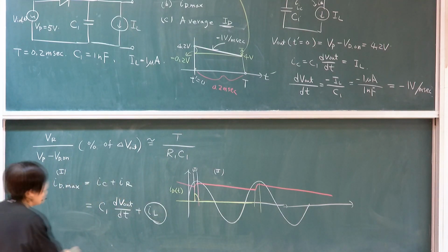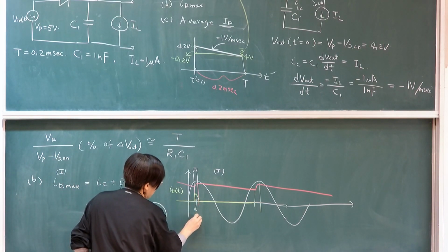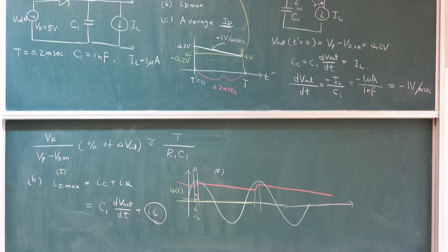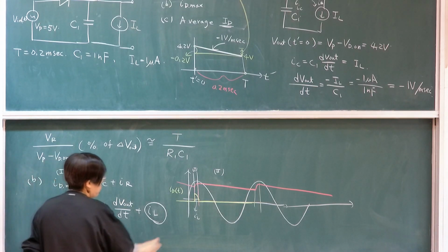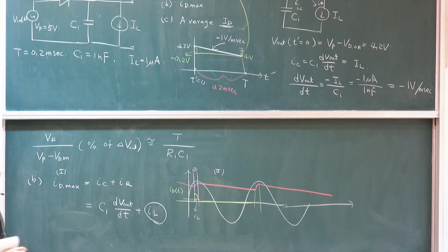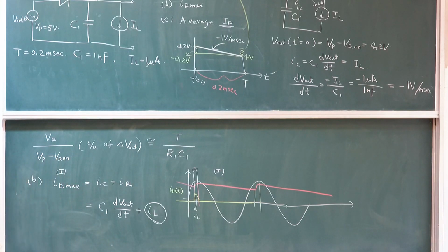I don't know if this is clear enough, so I will explain a little bit. You always have a baseline because you need to supply a base of I load. So there's a flat I load plus a, I should say cosine, because the derivative of sine becomes cosine. So part of the cosine plus I load. So that's how you get that. We'll need to find the peak level when we find out this time. You need to know the time in order to get the peak. So it's slightly more complicated, but I'm just giving you a sense as to what needs to be supplied.